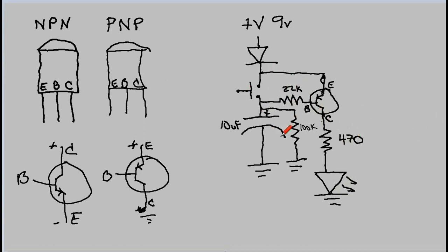Okay, so let's see what happens with this circuit when we turn it on. Well, actually, right now, if that's plus volts, this light is on. There is nothing shutting it off. So this LED right here is actually on right now. Now remember, with the NPN circuit, we had to push the button to get voltage to turn on the light. Well, right now this voltage is on. When we add voltage pressure, it's going to shut off the LED. So it's going to do the exact opposite. And that's what's great about the NPN or the PNP. You've got opposite results. So no matter what you're trying to do in the switch, if you want to turn it on or off depending on whether there's voltage or not, you just choose an NPN or a PNP.